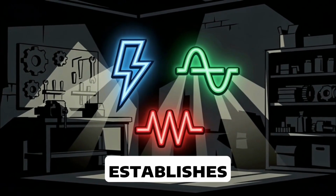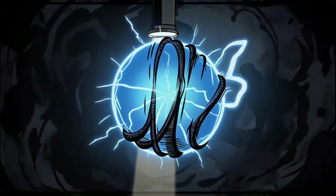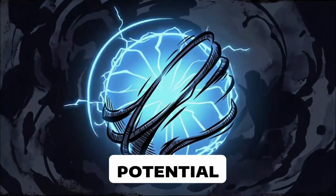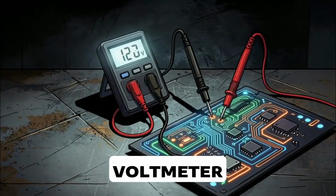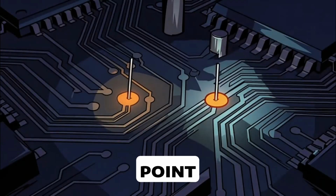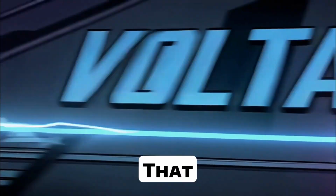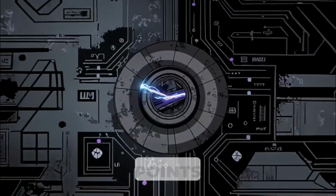Once the chapter establishes the electrical pathway, it defines the three most important electrical terms: voltage, current, and resistance. Voltage is electrical pressure, also called electromotive force, potential difference, or simply voltage. The symbol commonly used is E or V. A voltmeter measures the difference in electrical pressure between 2 points in a circuit. One point by itself does not have voltage unless it is compared to another point. That is a key exam idea. Voltage is always a difference between 2 points.